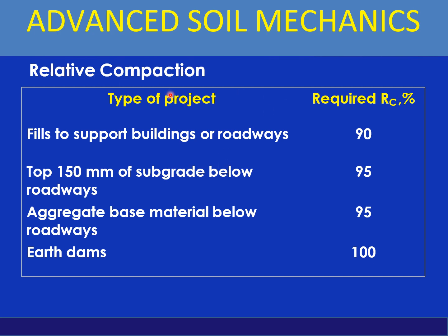Relative compaction: fills to support buildings or roadway, 90% at least. Top 150 mm subgrade below roadways, 95%. Aggregate base material below roadways, 95%, and earthen dams, 100%.